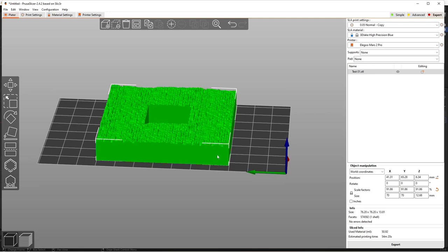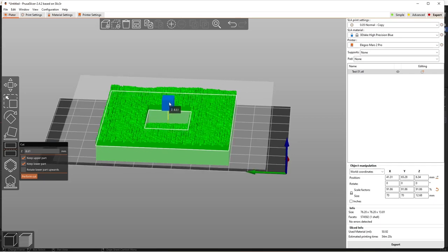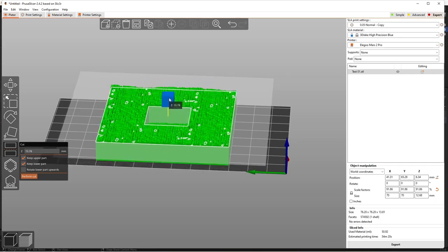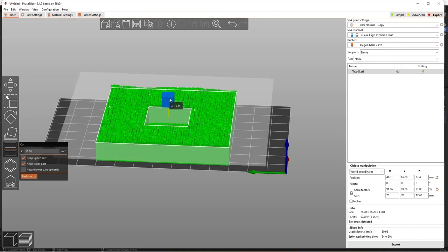Now that's a bit too chunky for our wall, need to slice it off, so click on your object and we'll do a cut. Now if we move this up, we start to break in to our brickwork. So if we come to the bottom of our brickwork, on here it's got 10.44.